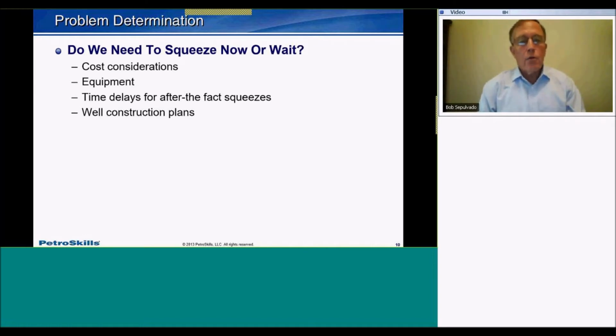We just talked about the equipment. Time delays for after-the-fact squeezes: you have to wait on cement, wait for it to set, go in and drill out. In well construction plans, if you're squeezing, you may have to put additional perforations into the casing, into the pipe, and nobody wants any more additional holes in the pipe than need be.